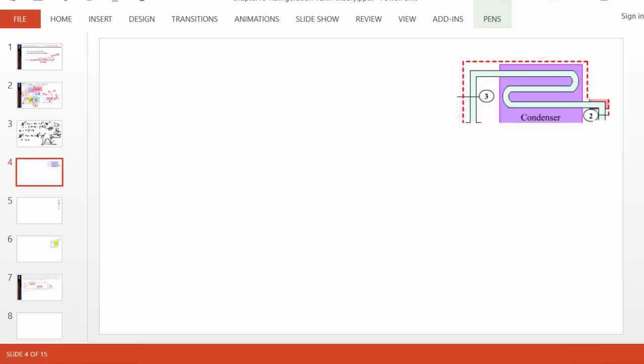Okay, let's move to the condenser. Again, let's quickly use the energy equation. In a condenser, heat is coming out, Q dot out or Q dot H, whatever you want to call it. So energy that goes in, energy that comes out, Q dot H will be the difference between that, and you can practically write it without going into the energy equation. What is Q dot H? The energy that goes in is higher than the energy that comes out with the flow. So the difference must be heat that is coming out, Q dot H or Q dot out, whatever way you want to describe it.